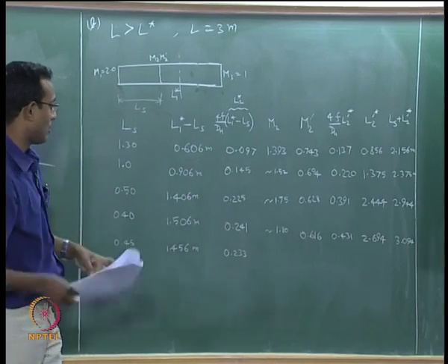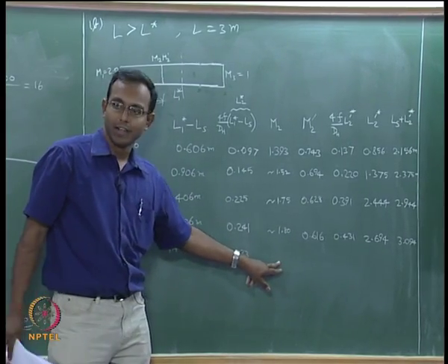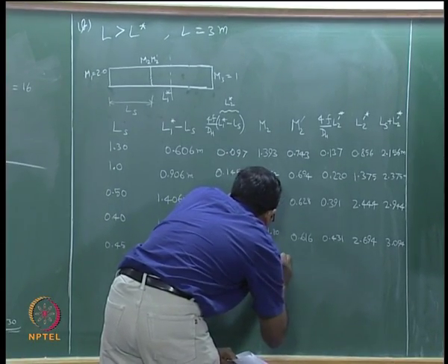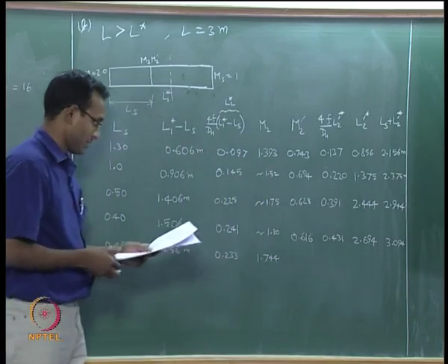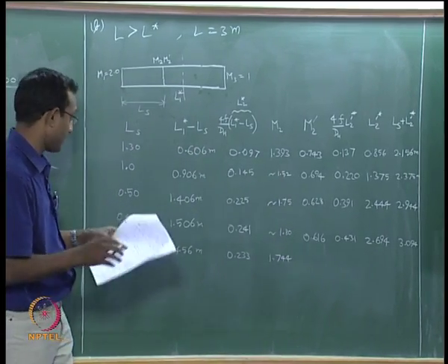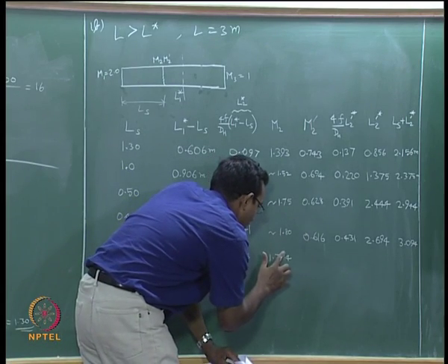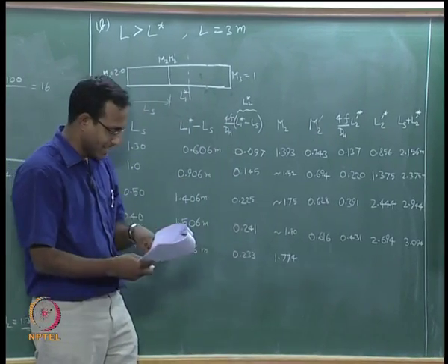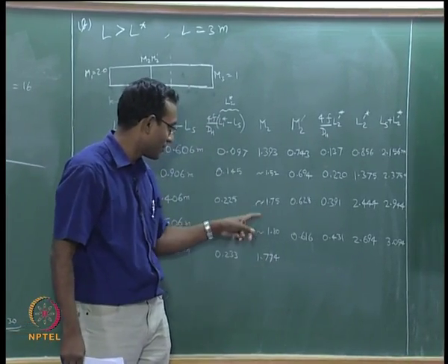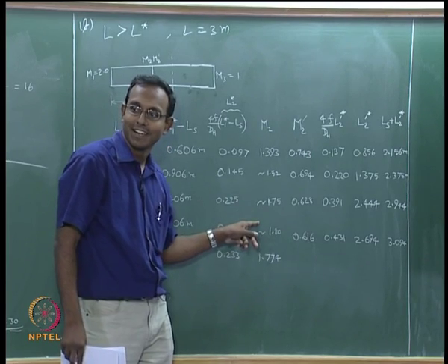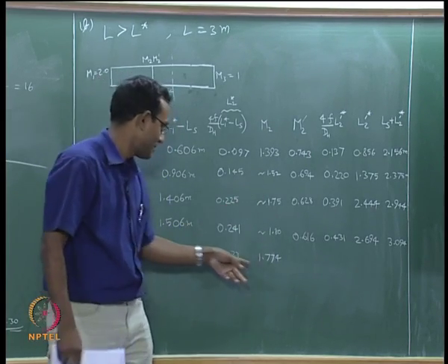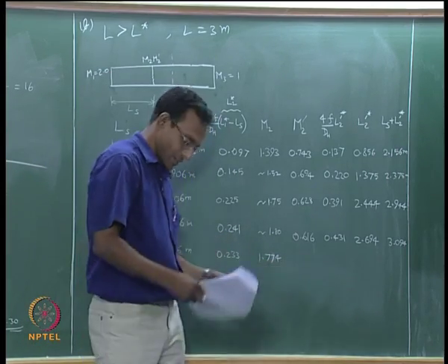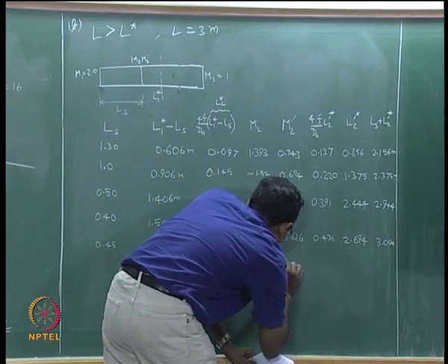Now from here I want to go find Mach number ahead of shock, that value now I will do it more carefully, no more approximate methods, doing it a little more careful, 1.774, sorry, 1.774. Of course, the way I checked my answer was because 1.744 was not in between these two numbers. Okay, when you are iterating, just go through these simple checks. Okay, 1.774. Now I will go look at normal shock tables, and that gives me 0.623.